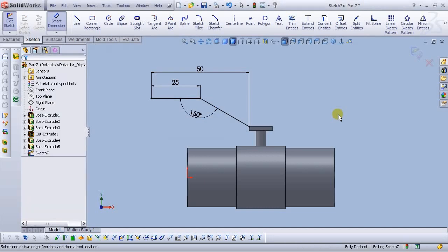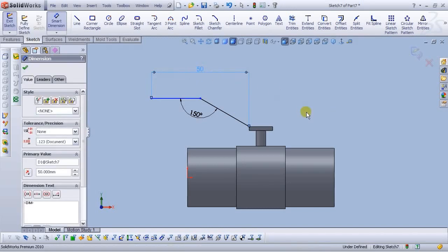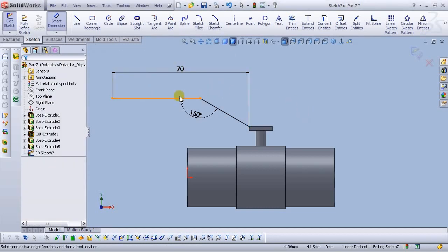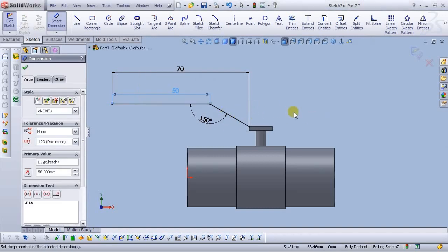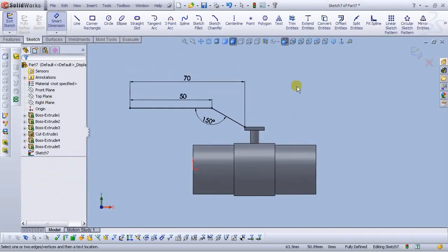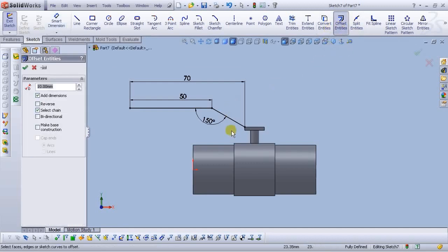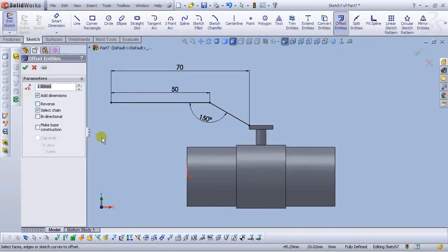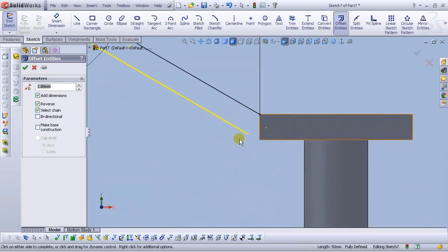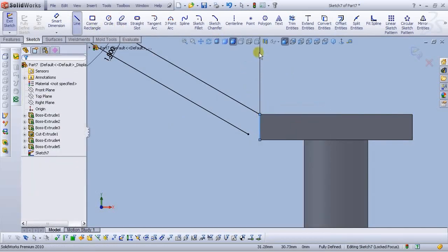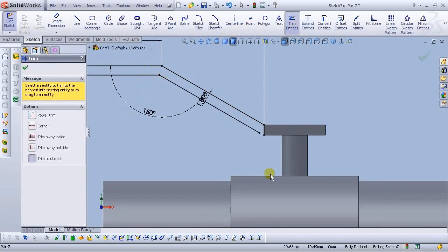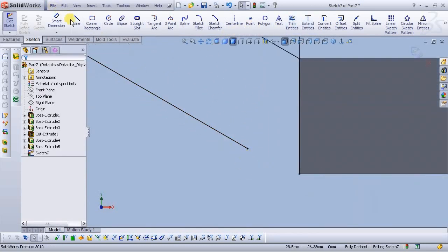Let's open a new sketch on this face here. Sketch, normal to view. Let's draw a corner rectangle. Okay. From this line, select 12 millimeters from this side, and for this side, select 7 millimeters. Okay. Go to isometric view and go to Features, extrude boss base, and for the depth, type 2 millimeters. Select OK. Looks good.